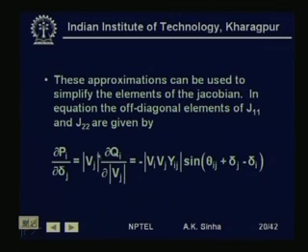Now, here what happens is this term will be a summation of all these terms, whereas we know that the term for B_ij is the negative of the susceptance of the actual admittance Y_ij for the line connecting bus i and j, and B_ii is a term which is the sum of all the susceptances connected to that bus.